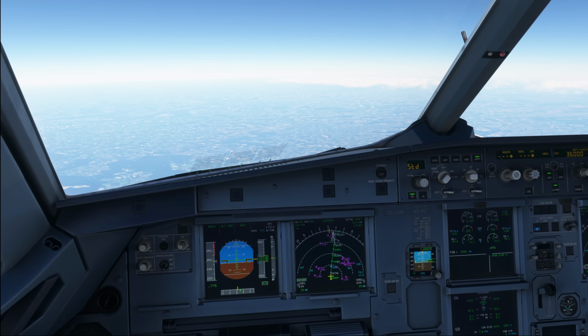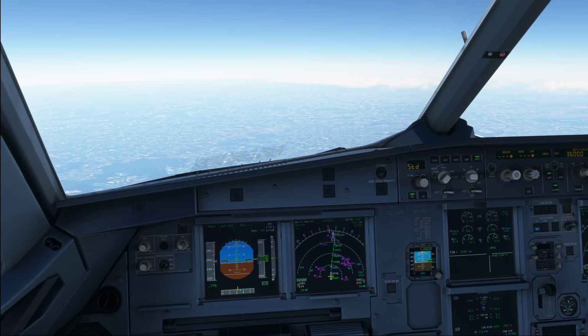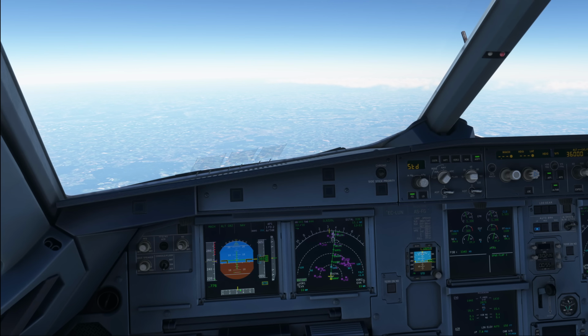Now, the next point then is takeoff runway optimization. The takeoff performance is the first factor to consider in the selection of the takeoff runway. When possible, however, the flight crew should request takeoff on the runway that minimizes taxi time and optimizes the departure trajectory in order to minimize the flight time.